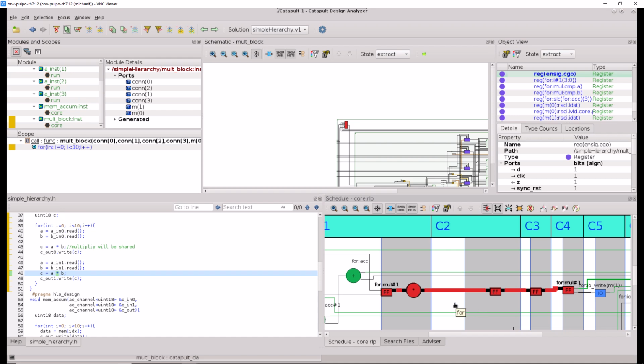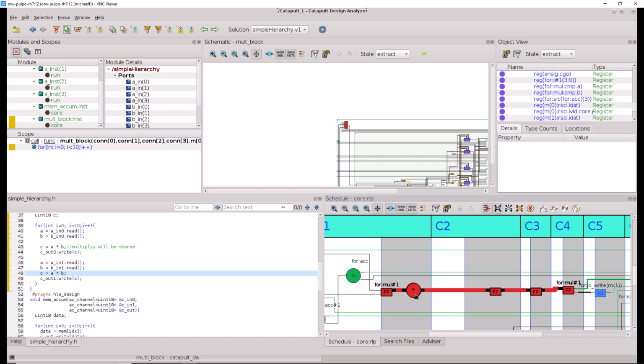The current version of Design Analyzer is not capable of showing the input to register delay or the clock to out delay, and simply indicates the number of sequential stages by the FF symbol that is part of the pipeline multiplier symbol. So we can see here that there are 4 register stages in this pipeline multiplier implementation.